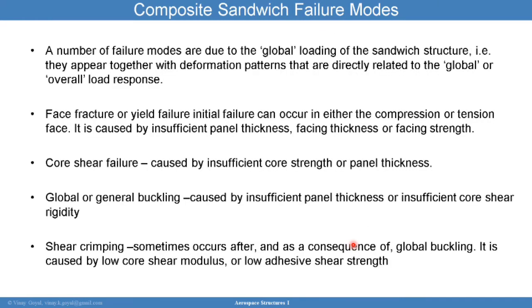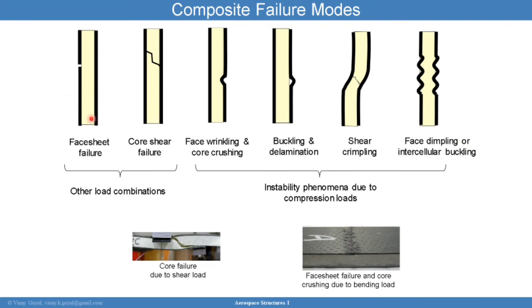Composite sandwich failure modes: there are a number of failure modes that are due to the global loading of the sandwich structure. They appear together with deformation patterns that are directly related to the global or overall response. And let me go through face sheet fractures. So that's the one I covered earlier. It could be either compression or tension. So I'm covering this one right here.